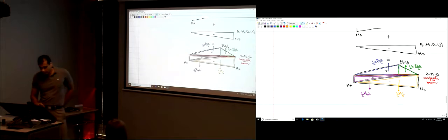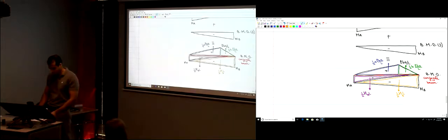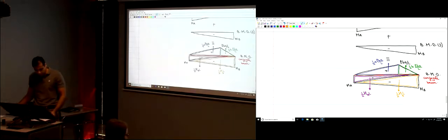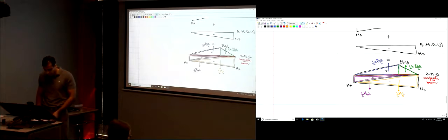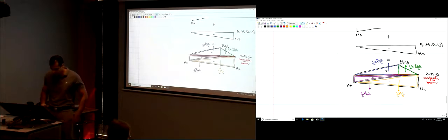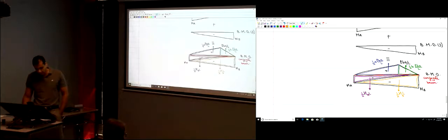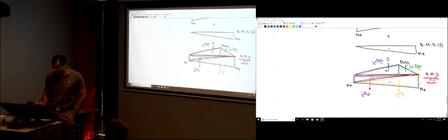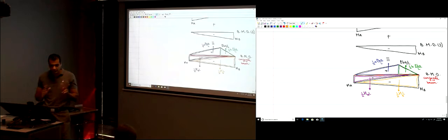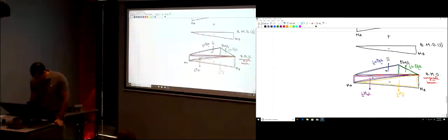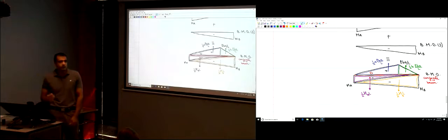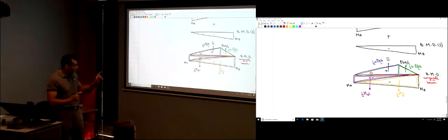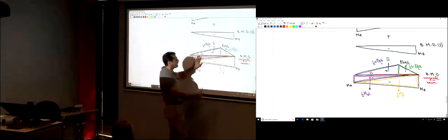So we have those 4 forces. Now, for the equilibrium of the conjugate beam, our target is to find MA and MB. So we have 2 unknowns here, MA and MB. We want to find each one of them. To do this, I'm just going to label this point here, point D. And then I'm going to take moment about point D to find how much is MB.